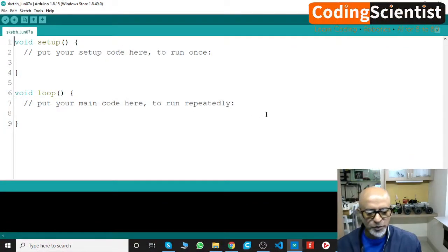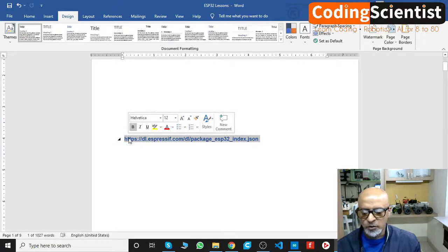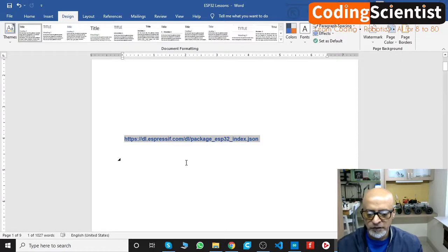Once you open up your IDE, there is a link that we need. It's here in my Word document. I am going to copy this link. This is from espressif.com, who are basically the manufacturers of ESP32. This particular package we need to configure into our IDE. I am going to leave this link below this video.